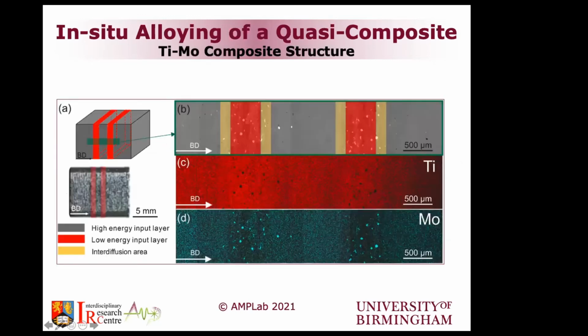So basically, in some layers, he would fire the laser at a maximum power or the required heat input to dissolve everything. And then in other layers, he would not dissolve the moly. And then again, dissolve most of the moly and then leave a little bit of moly. And basically creating that kind of sandwich structure of on and off to see if that's going to give us any improvement in the mechanical behavior or not. I mean, now, obviously, I tried to tell him to take it easy because obviously those undissolved moly will have an impact on mechanical properties, but at least on the tensile. But we wanted to look initially onto the compressive.